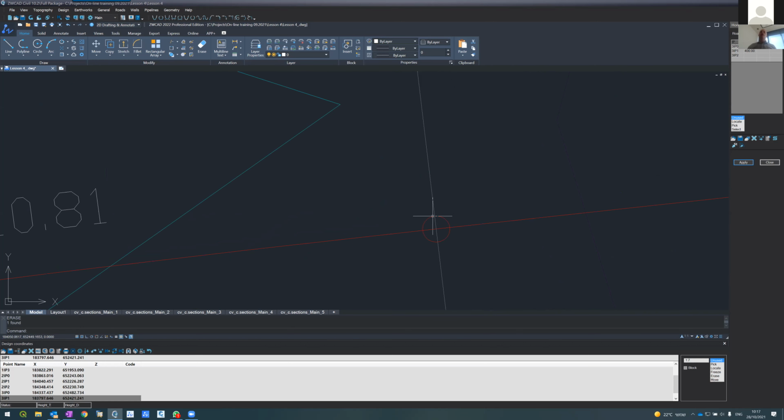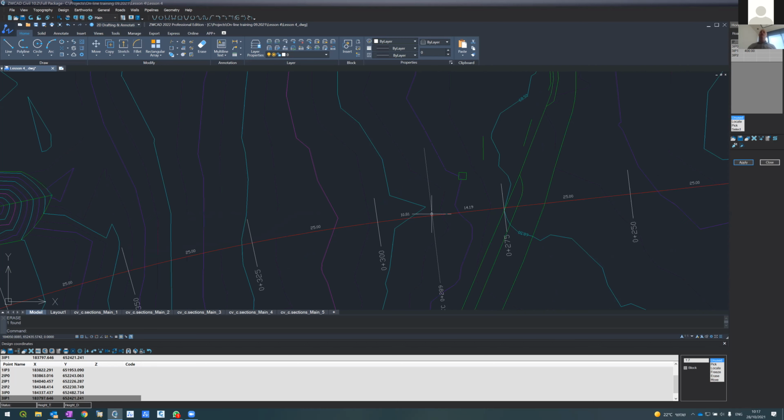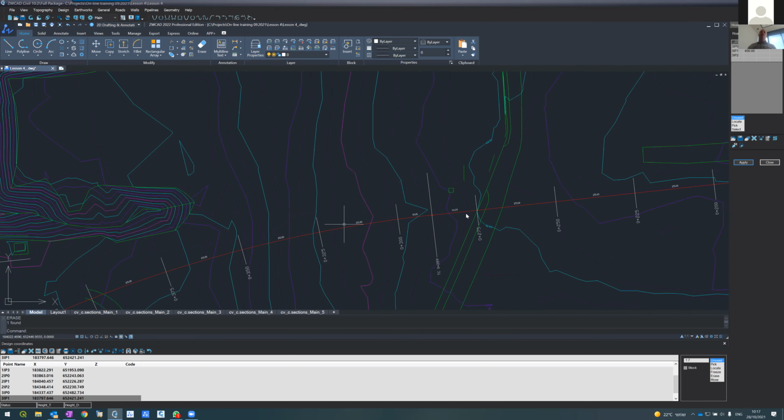And I want to create a transition curve here using a clothoid. So the transition here, the runoff, would be from here to here, let's say a runoff of 30 meters. And the same runoff, same transition, I will do here, 30 meters here.